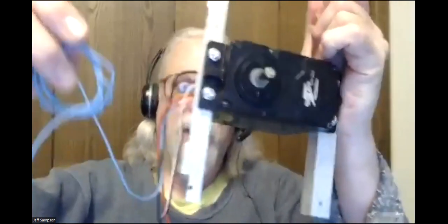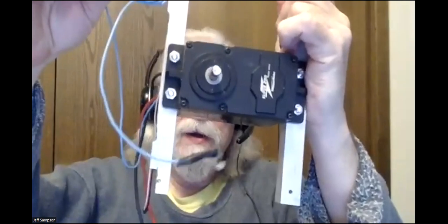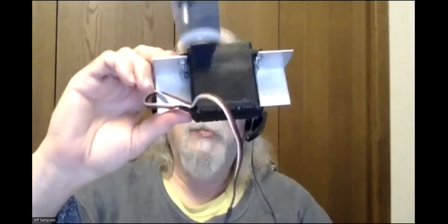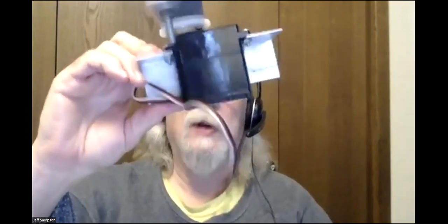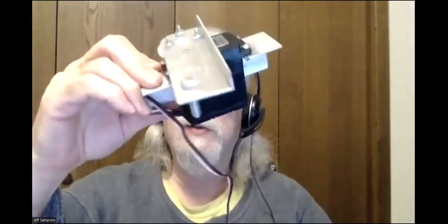And then I can plug in my Super Servo 200, and this blue wire is the feedback wire that I put on the thing. So, technically I can try any of those. And I assume if I go into just a standard servo like this, that's like quarter scale, if I solder a wire to the pot inside, I can do exactly the same thing. So I could check it against real servos, as opposed to this one that somebody's hacked up. So that would be an interesting thing to do.